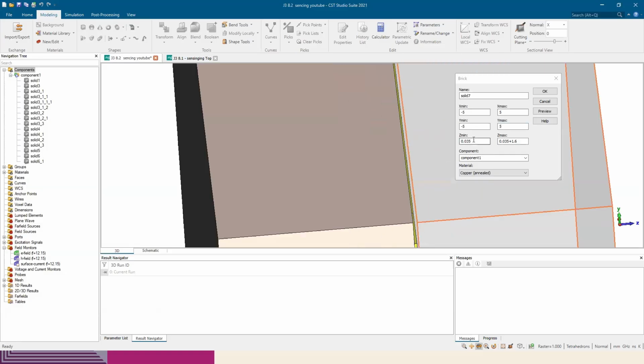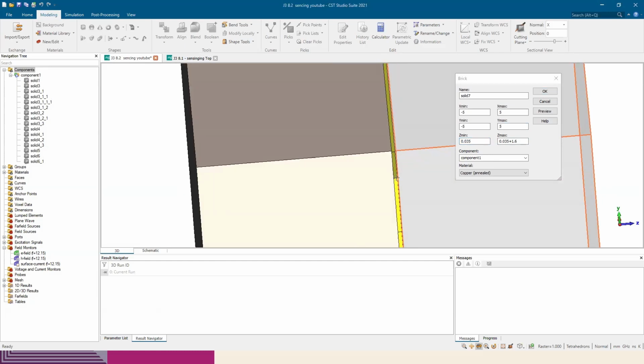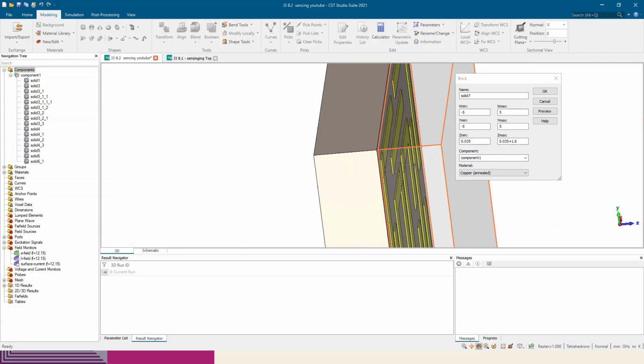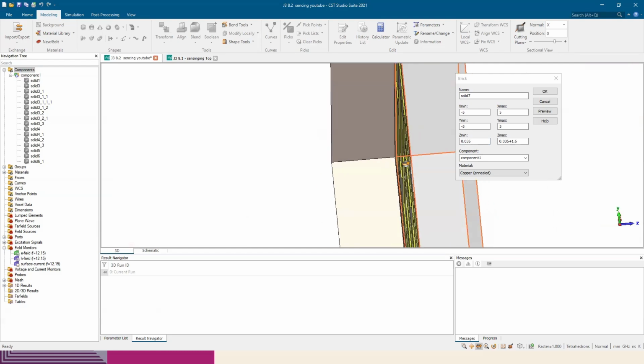And why I started from 0.5, not 0, is because there is the copper layer. This copper layer has a height of 0.35 millimeter. If I just started from 0, this material would overlap with the copper. So it would be theoretically wrong, because in the general case you will not be able to put the metamaterial and the testing object in the same place. You will be putting it on top of the copper.